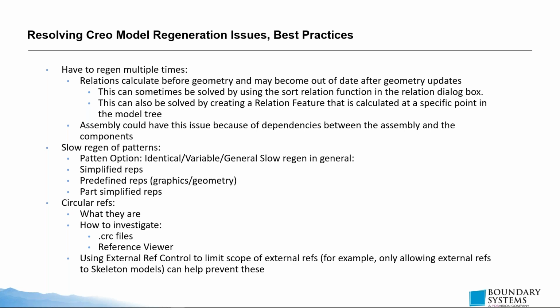Well, once again, with that, relations calculate before the geometry and may become outdated before the geometry updates. So once again, depending on the order that we've written our relations, we may be updating some geometry before or after a relation actually looks at the value of that geometry.